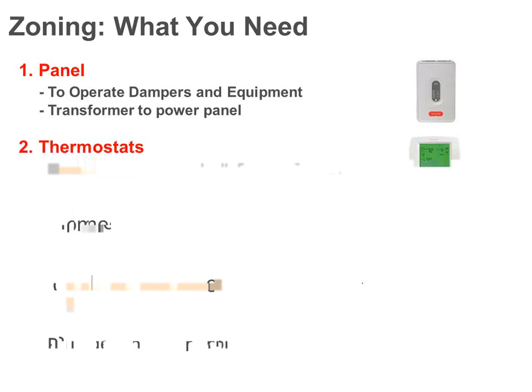The way we normally do that is with a bypass damper. So that damper opens up and dumps air from the supply duct back into the return duct to relieve the pressure problem. Now, granted, when using variable speed furnaces, the problem is minimized because a lot of times if you only have one zone calling for heating or cooling, you are at a lower airflow setting on the furnace anyway. However, it's still possible you have too much airflow, so you still do need to have that bypass. And then we also need a sensor in the discharge air temperature to protect the equipment, and we'll talk about that in a second.